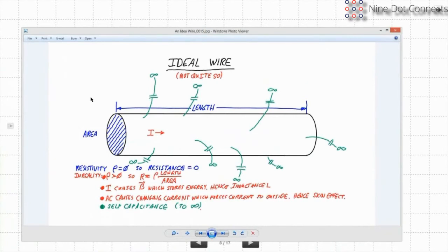But even with superconducting, there's a current threshold where you can't go over that. It just can't conduct it, and then it does become resistive. So in reality, it is resistive. It has resistivity, and it turns out that it's going to be the length over the area. If you take the length to area ratio multiplied by the resistivity, you'll get the resistance of that length of wire. What else is wrong with it in terms of being an ideal thing?